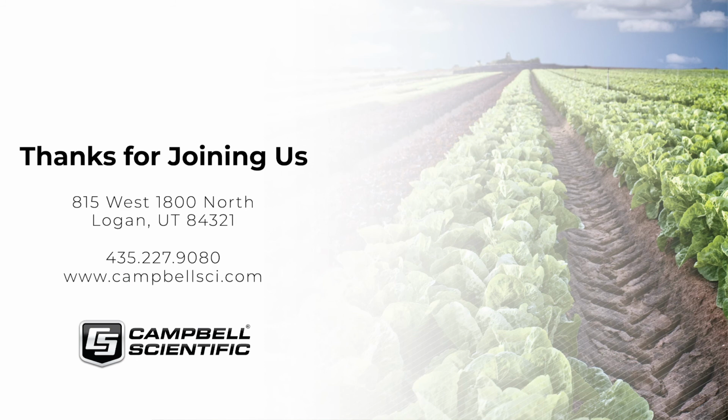The amount of salts in your soil mainly changes the conductivity. And it's that conductivity, that ionic loss, that causes problems in your sensor. So the measurement of conductivity is going to give us probably more than just a quantity of salts or the total dissolved solids.